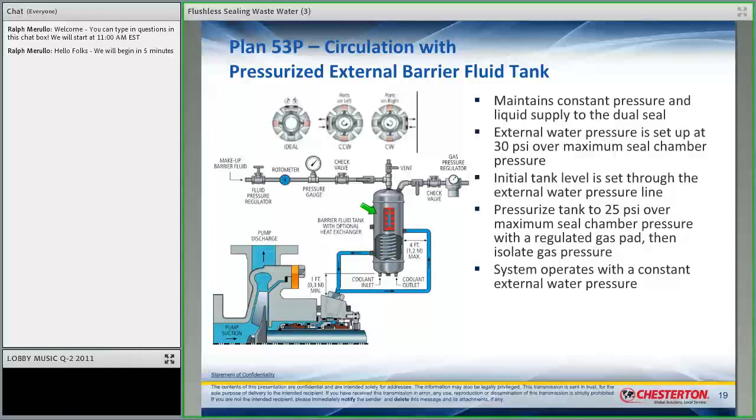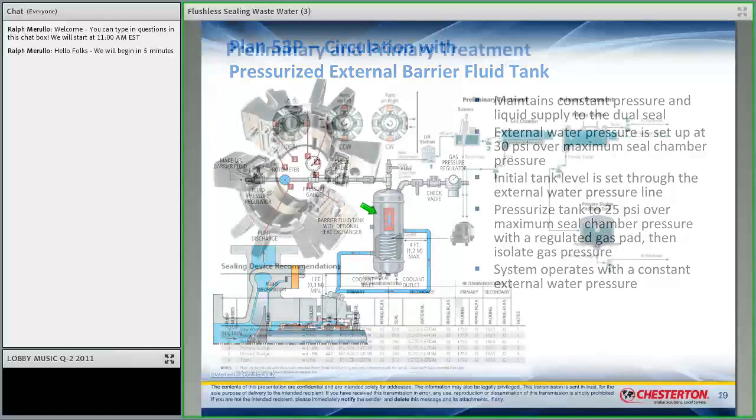And a lot of times the lift stations are remote, so you don't necessarily have a lot of water out of that lift station, right? So how are you going to do that? So this is some of the challenge that we have to think about. When we have a lift station, do we have fiber in our flow? Do we have, before it gets to the lift station, some way to remove this fiber? There are machines that do this instead of doing it at the pump. Are we using pumps that are chopper pumps? Are we using conventional pumps? So these are all things to consider. But anyway, as a seal vendor, this is one way that we can solve this problem if the customer is willing to do that.